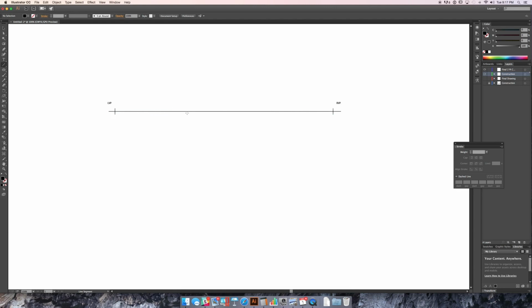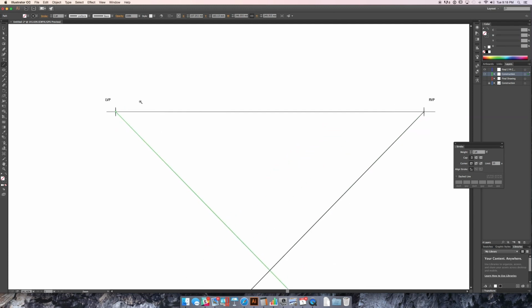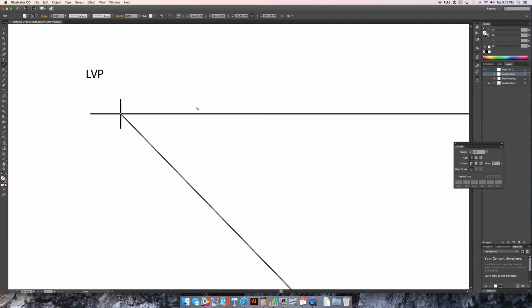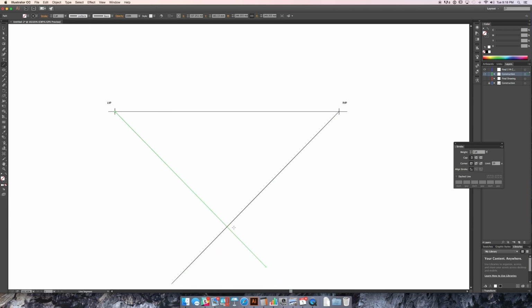So I can do that in a couple ways. One is I can take a line starting right here where it says intersect, holding Shift and dragging down. That'll give me a 45-degree line from that point. I do the same thing on the left. Double check here, I'm drawing from that central point. And now where these 2 lines intersect, if I draw up, that's going to be the center of the distance between those 2 points.